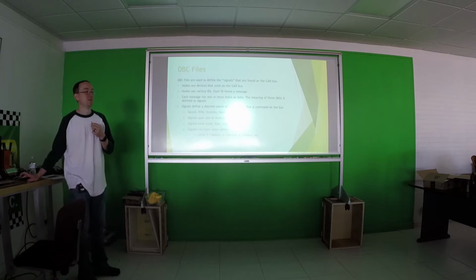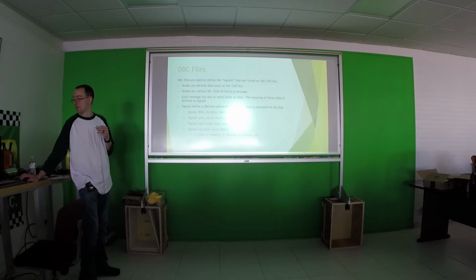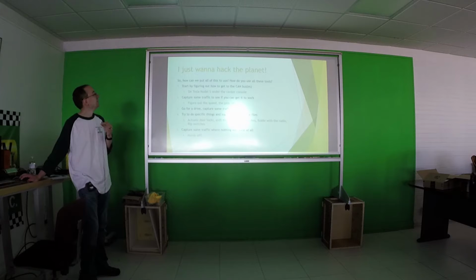If you have a DBC file, we have one. Yeah, we do have DBC files for some of the things, and it is basically a dictionary. It's where you look up what all the data bytes are, what do they do? And it's a way of keeping track of it. So it's a dictionary file for CAN. This would be a little more clear. I'll show you in SavvyCAN how the DBC functionality works. That'll probably clear up the way it...